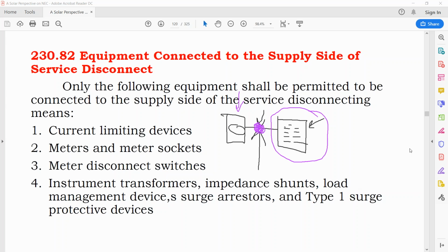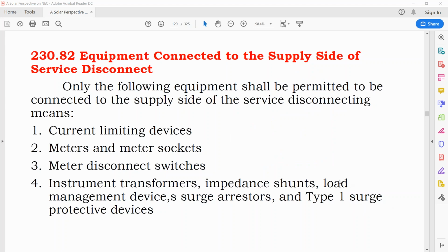What I typically do is, here's my very crude house, and I'll put my solar array on top, and then I'll run some conduit through the roof and then out the soffit. And so my inverter's on the outside of the building. Being able to tap onto the service entrance conductors is convenient. So when can you do that?